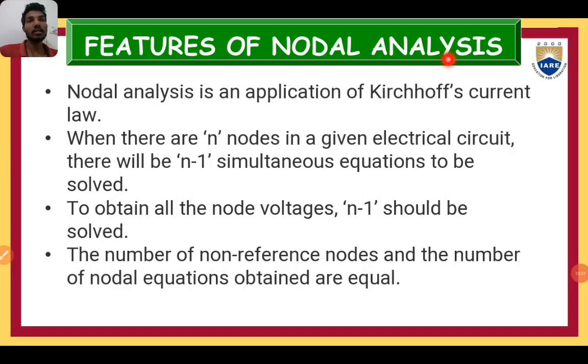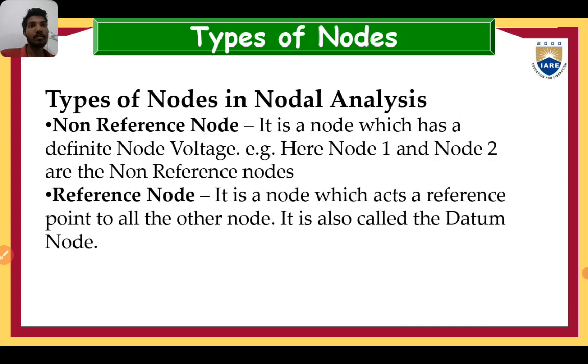Features of nodal analysis. Nodal analysis is an application of Kirchhoff's current law. When there are n nodes in the given electrical circuit, there will be n-1 simultaneous equations to be solved. To obtain all the nodal voltages, the n-1 equations should be solved. The number of non-reference nodes and the number of nodal equations obtained are equal.